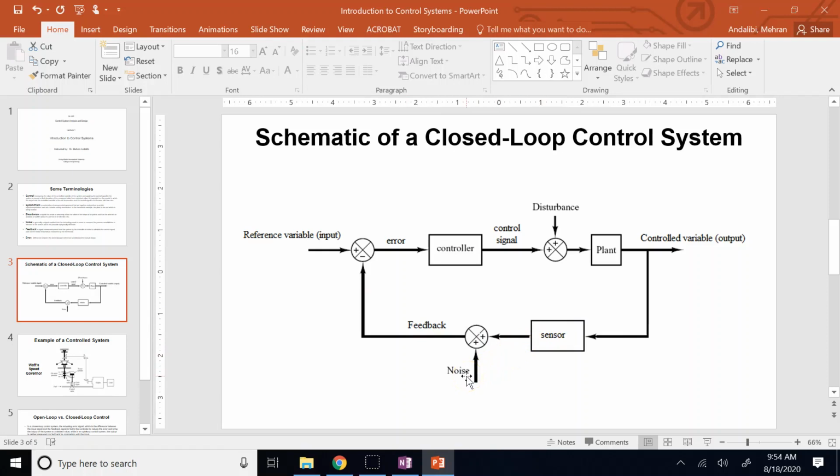So we cannot just remove them, but we can mitigate their effect later when we send those feedback signals into the control, or we can put them right after the sensor. So a portion of the controller can be right here. Before you compare it against the inputs, you can do some filtering here, okay?